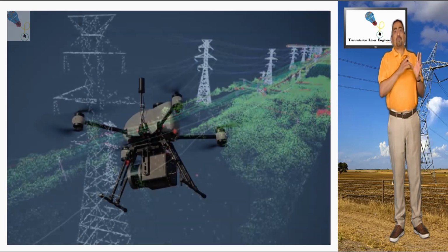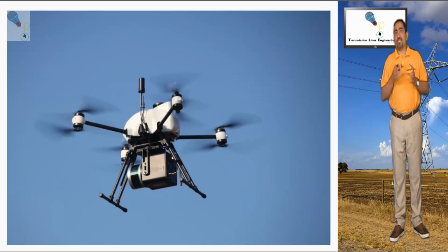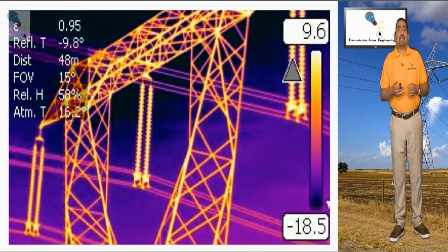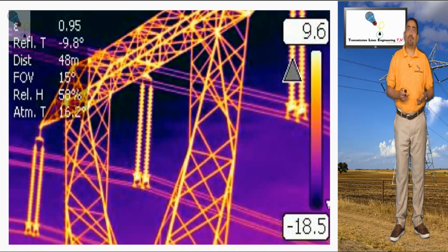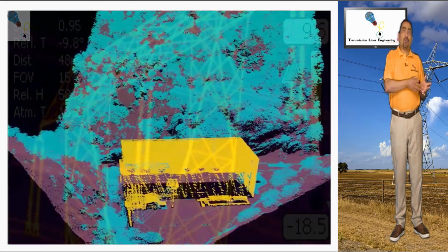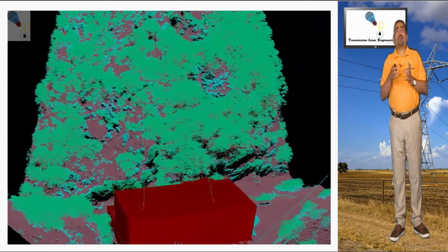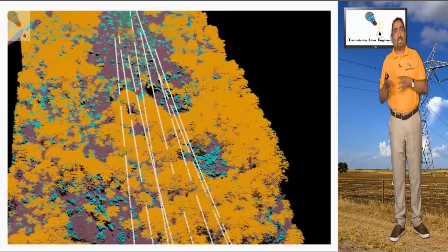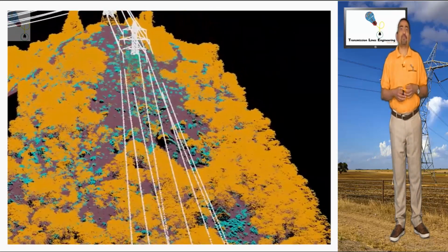Depending on the services requested, other types of scanners can be mounted on the aircraft, such as aerial photography and thermal survey for existing cables, to later know the ampacity and temperature of the existing cables during the flight. And as a result, you get a series of reading points which contain information about the coordinates and elevation.